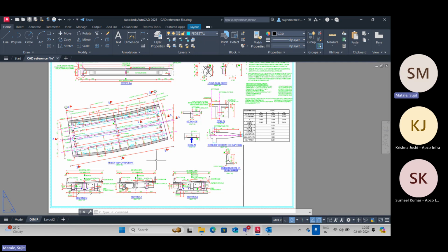Now, to these line elements you need to assign cross-section properties. For cross-section properties, you will need materials. So the workflow is such that you start by defining nodes and your structural elements, basically developing a geometry. You define materials and cross-sections, and assign the cross-sections to the elements you are modeling.